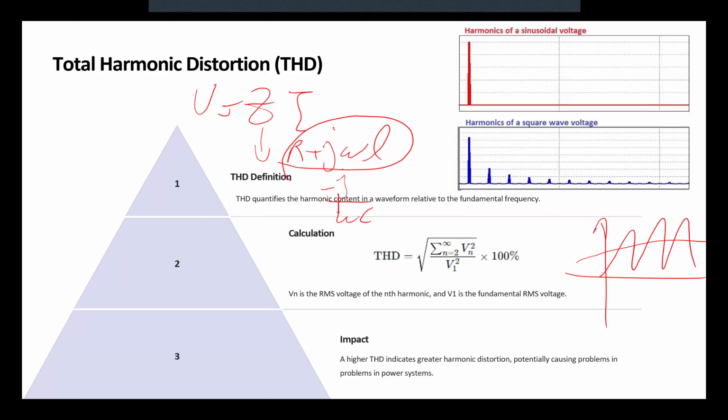If I reduce the modulation index, so damp my reference signal, what's going to happen? All the harmonic amplitudes are going to be damped. If I push this reference signal towards zero, my third, fifth, and seventh harmonics will significantly decrease because the amplitude is decreased, correct? But I also decrease my fundamental significantly.